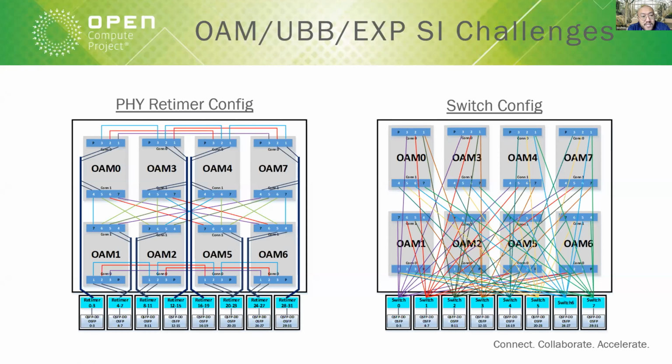So right now in this presentation, we focus on the PHY retimer config. We did some examples. We did layout, post layout, fabrication, simulation, and we did some fabrication of the scale up card with the latest class 8 material, and did the measurements. However, in today's presentation, I'm going to present the example of the SI full wave simulation, which is post layout